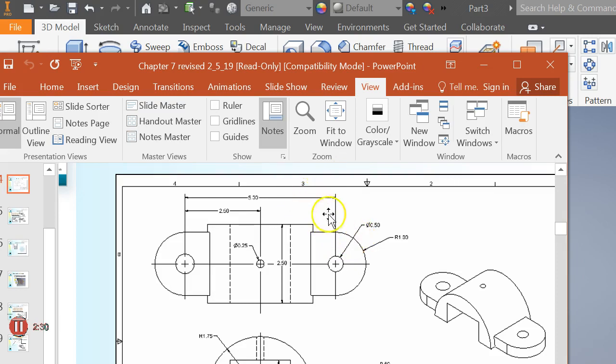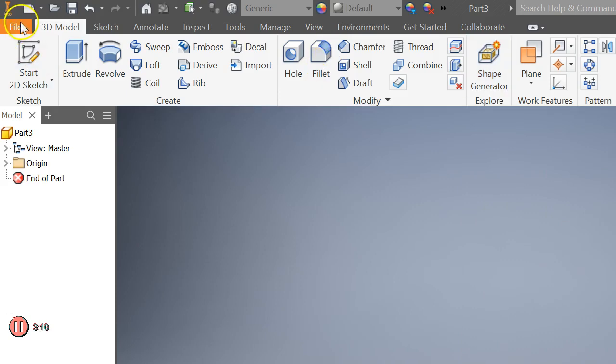Looking at this portion at the bottom, slot is an option of rectangle, and that's what I'm going to use to draw that. Looking at this particular object, I can see that this second sketch, which is the half round part, is going to be extruded differently than the bottom part is wide. So if I set up my 0, 0, 0 at the very center of this part, then I'll be able to extrude this one symmetrically. Now, you could do something else. As long as you know where 0 is, you should be fine. So I'm going to minimize that and get started on this.